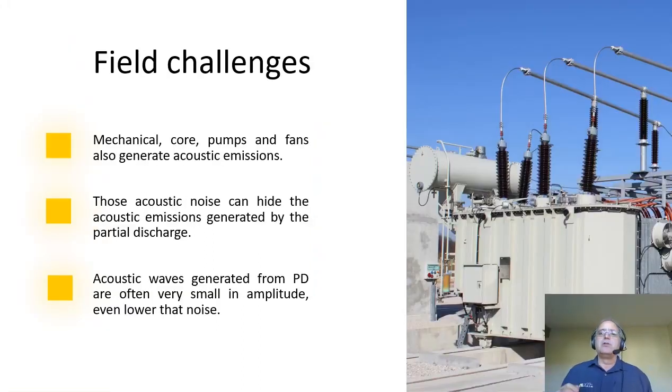The challenge is to remove the noise in order to see the time of arrival, because we're looking for a very, very small amount of energy within an energized transformer that is vibrating, that has pumps and fans, winds, vibrations, and lots of things on the field that will or can cover the time of arrival that we are looking for.